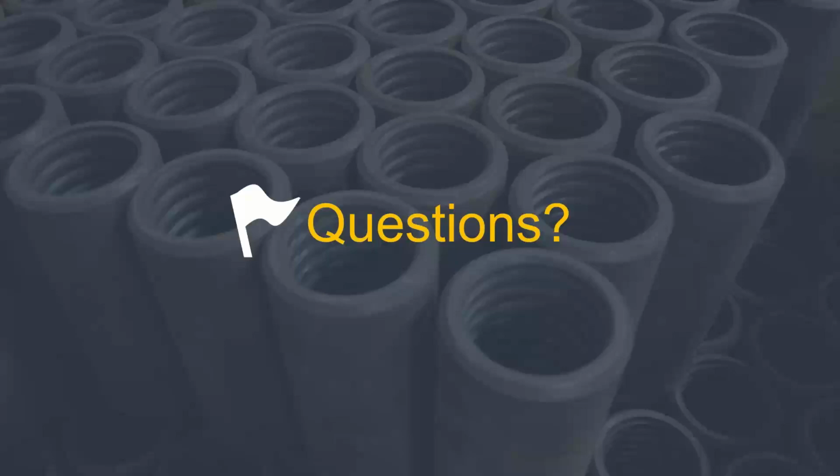You would hope that the engineer of record has already got a pile layout and is considering the amount of stability that they, as the structural engineer of record, are comfortable with. Because then that takes you out of designing it. But if you are in a situation where they haven't laid the piles out, you can just go in with 1 pile per column. You can do it that way, but if you have a design submittal that you need to work through, it may get brought up that that's probably not the most stable condition for your piles.